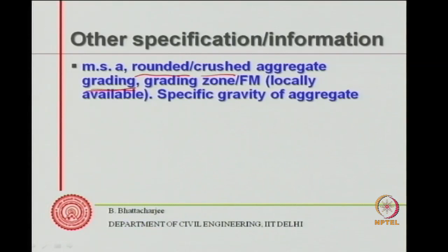Similarly, for sand, the grading zones may be important. Again, that's telling us what is the size fraction belonging to which size, the proportion belonging to each size fraction. Fineness modulus, also we have discussed sometime earlier, is again a kind of measure of an average size. So size of the aggregate, their packing characteristics, are governed by the shape of the aggregate, maximum size of aggregate, and proportion in each size.